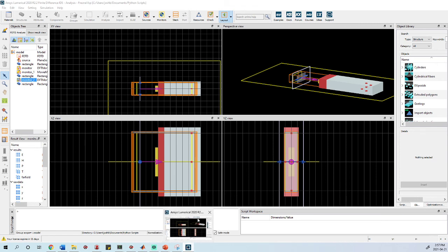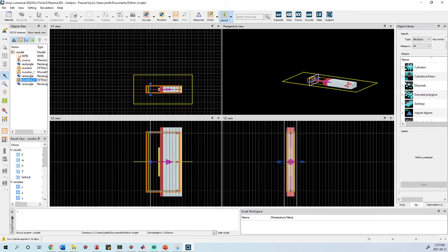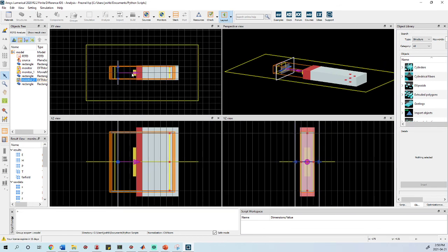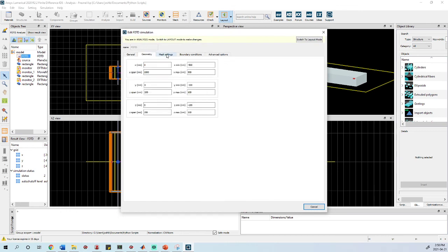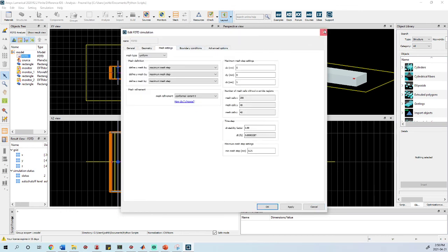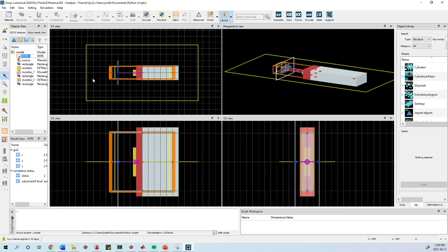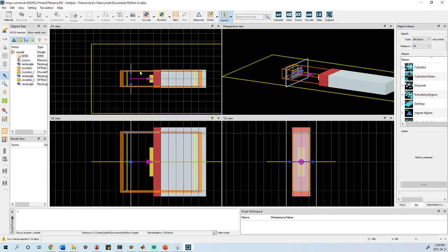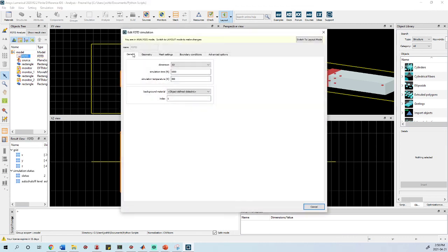What else could I show? Okay, let's do angled incidence waves. How about that? We want a wave coming in at an angle. The way we're going to do that is we're going to go into geometry. If you want to put in waves at an angle using FDTD with periodic boundary conditions, it's actually not as easy as you would think it would be.